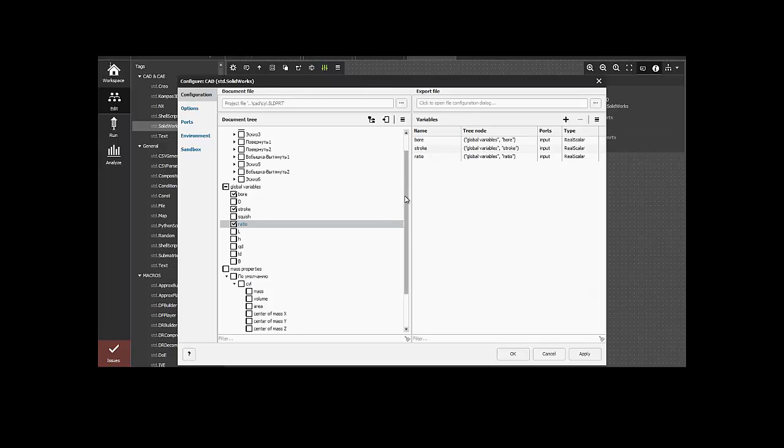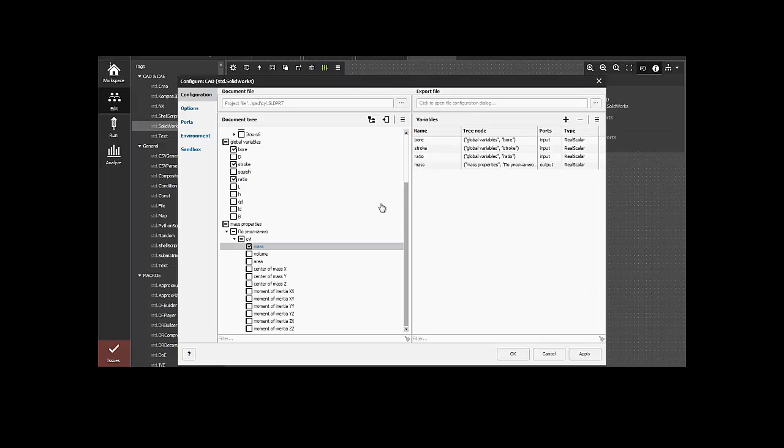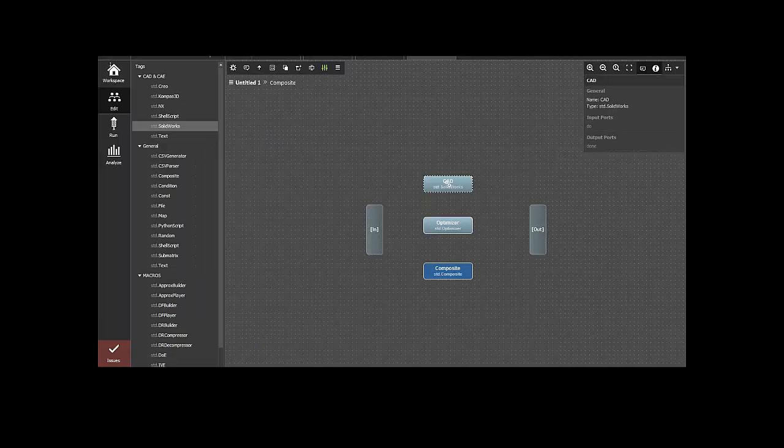And of course we want to get the mass as an output. So we will pass the inputs, the model will be rebuilt, and then the mass will be taken as a result of this block execution. So just that simple. Now we have this KD block to get the mass from parameters. We have this Amesim simulation to get the torque from our parameters. And the last thing we want to set up is the optimizer itself.